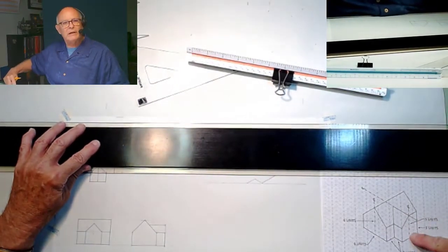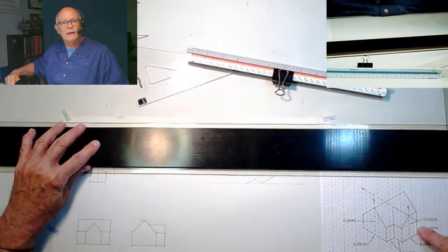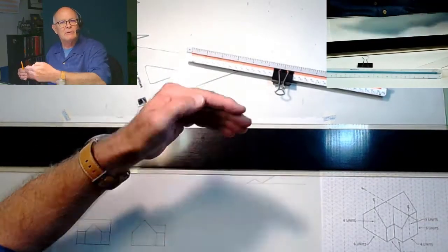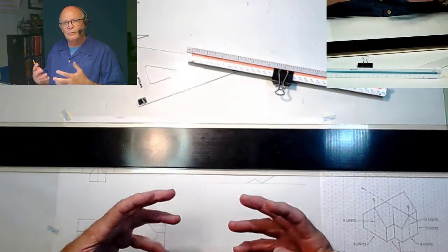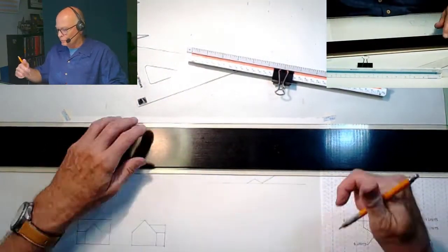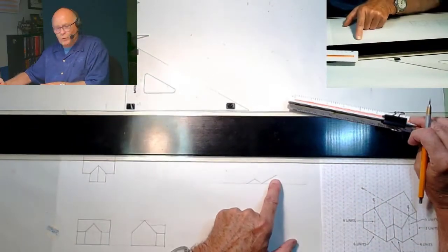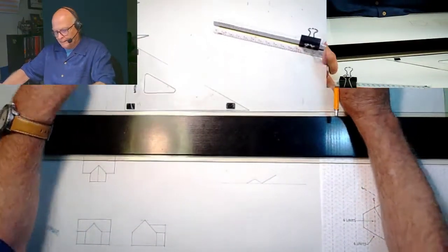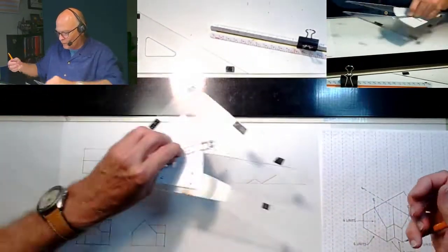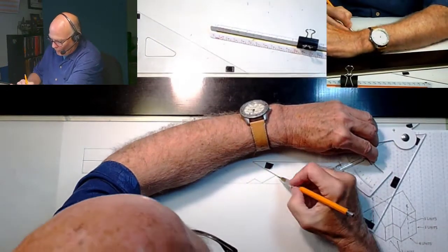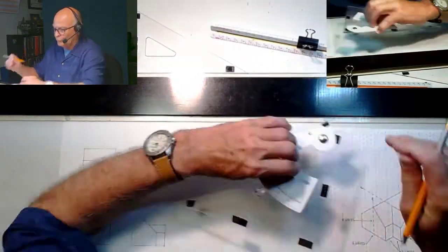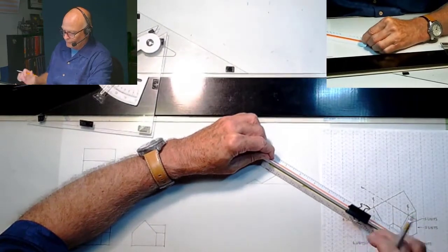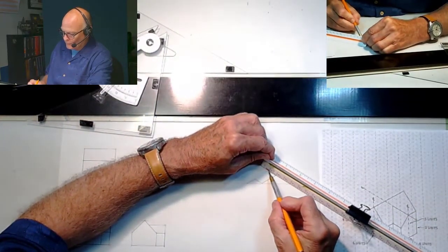We can't see that in this part of the drawing. We can, because it's hidden by the other elements that are drawn there in that 3-dimensional view. So we've drawn the front, now we're going to draw the back, or this part that we don't see. So how far back? It goes 2. We measure and we mark it.